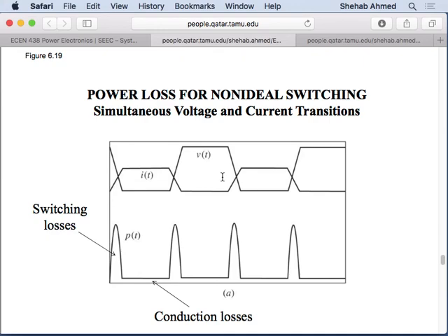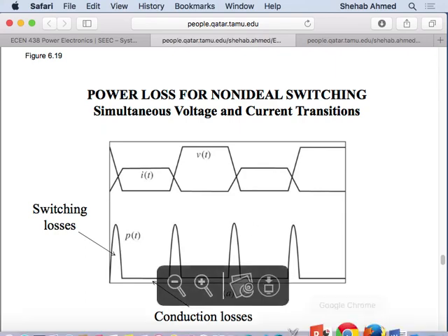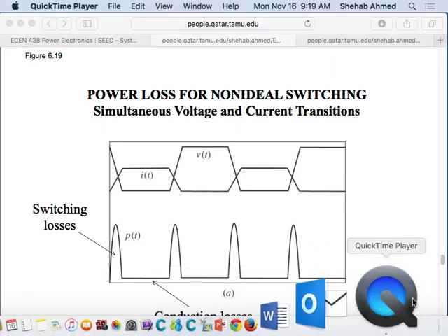Then we have a physical phenomenon in the inductance. It's peak current, maximum current, because that limits the amount of flux you can push through a core. And the capacitance, it's the peak voltage, because that's where the dielectric will break down, right? So that's how you select all 4 components without considering switching loss. So next class, we'll wrap up this chapter by considering switching loss.